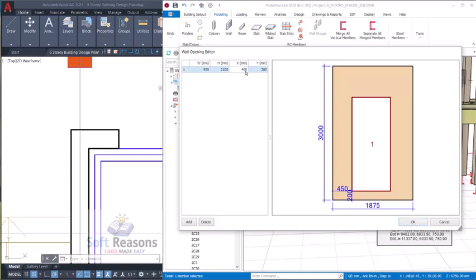So if you key in 375 here, this is not centralized, but if you key in 600, it may not also be centralized. So we go by 450 because the wall thickness is changed here. Wall thickness is changed. You can see we have changed the wall thickness to 300 by 300. So it all depends on you, the structural engineer, to decide based on their experience in design. So this is good. Click on the OK.